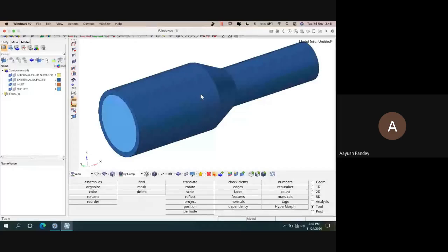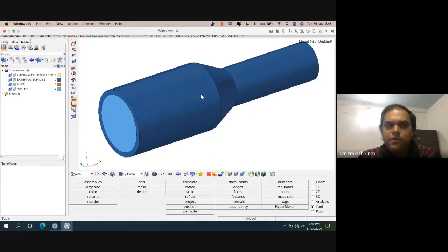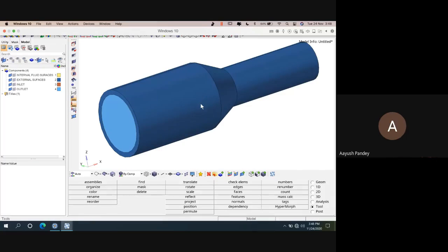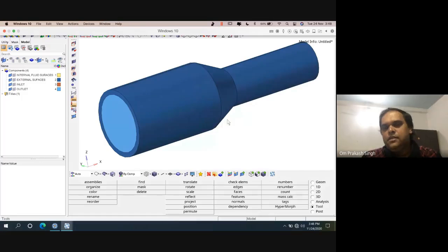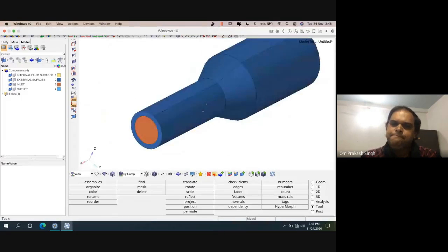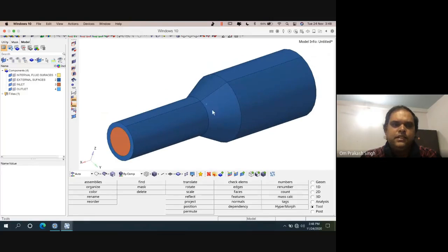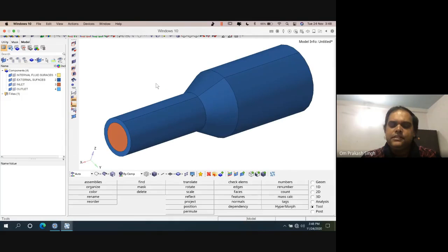Now see, how to check grid independence? How to check it on the software? Okay. See, let's say, you first start with a very coarse mesh without worrying about the exact result. Perform the simulation and measure whatever parameter you want, for example Mach number or some losses or velocity. That will not be the optimum, but you will be somewhere 30-40% maybe away from your accurate result. So next time, based upon the